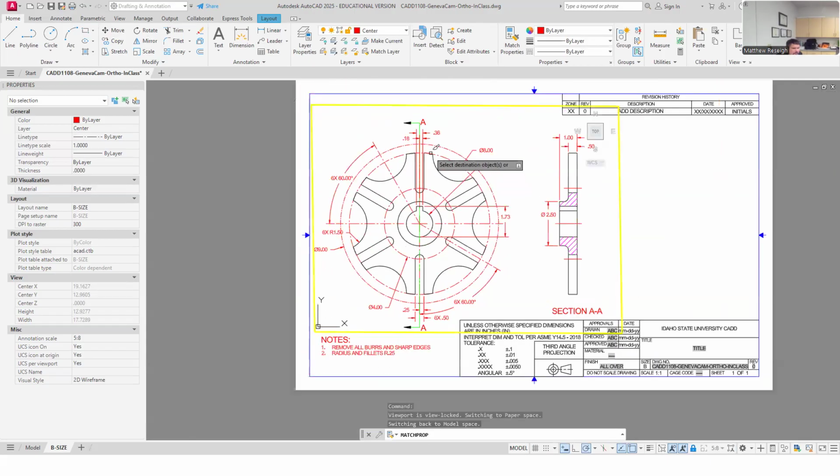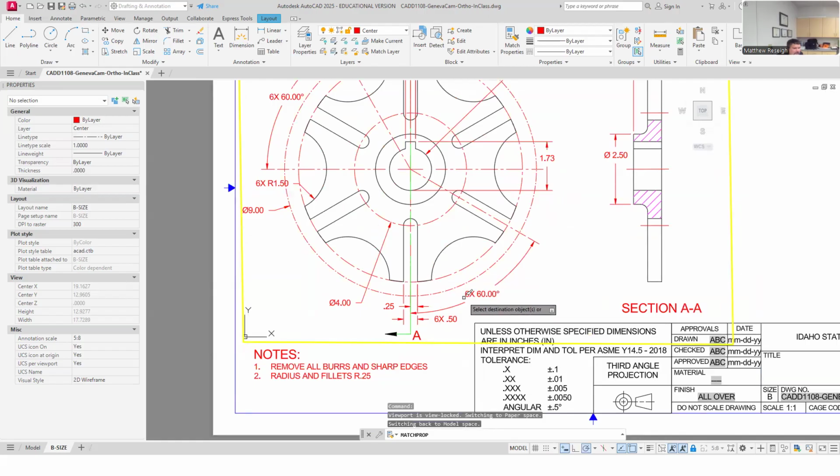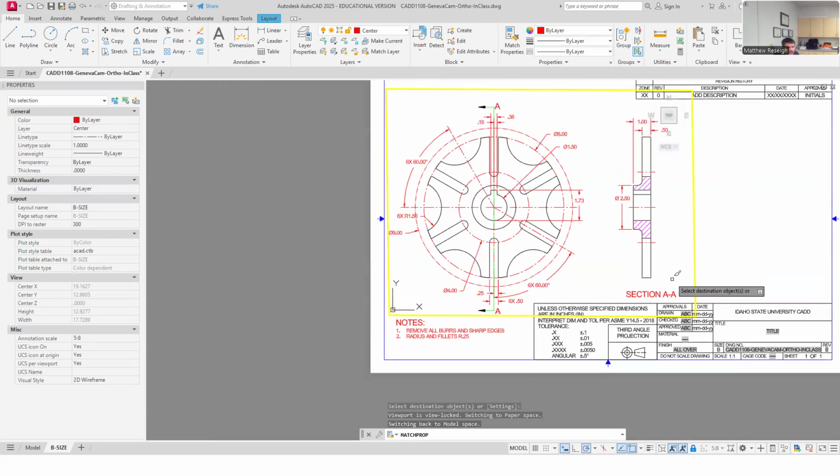Not too worried about the center one up and down because really the cutting plane line, I'm going to go back into my drawing and put it as precedence. It'll plot as precedence anyway because it's a heavier line weight. But I'm going to fix these ones while I'm in here real quick. These are half scale. I use 0.5. At least that breaks them up. That's good.